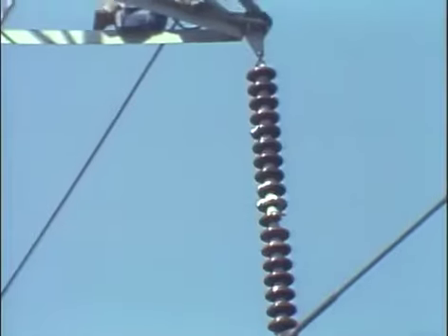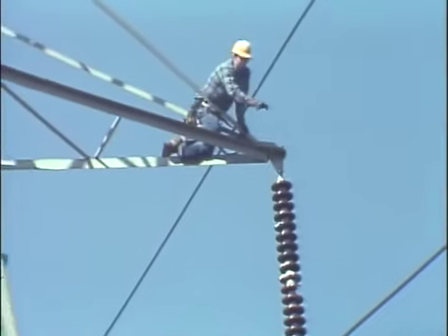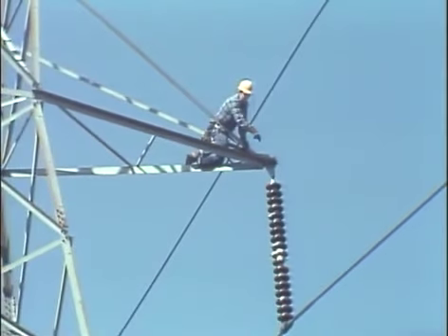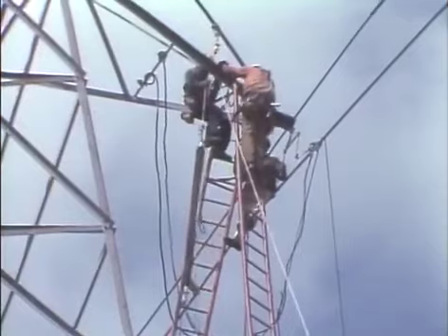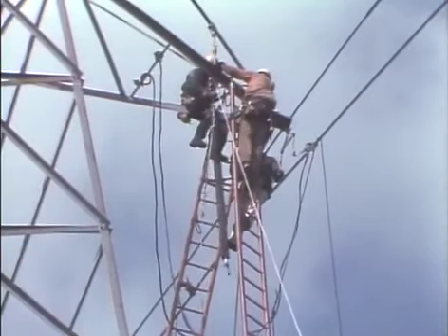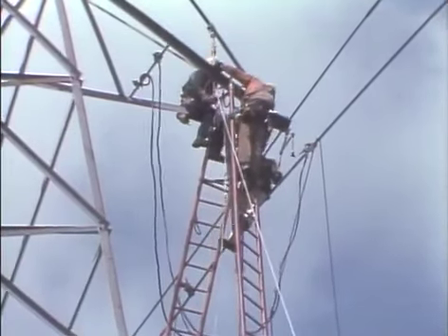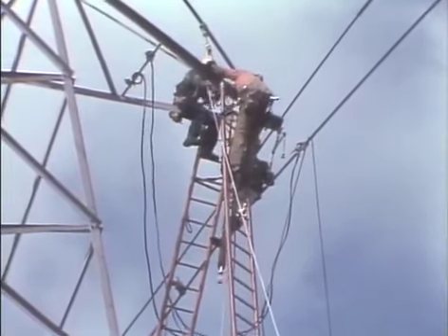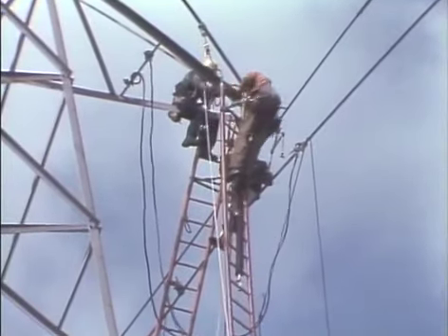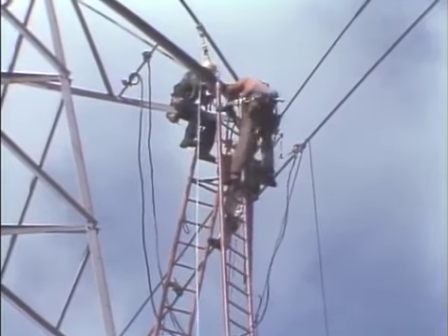The only factor a lineman can affect to change the capacitance of a transmission line is spacing. For example, let's say you had to replace a damaged insulator or stack on a transmission line. If you used a different insulator from the one in the plans, you could change the design configuration of the line by decreasing or increasing spacing. This would cause capacitance to increase or decrease from design specifications.